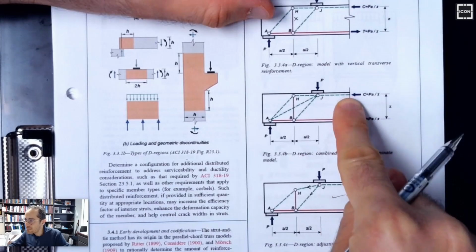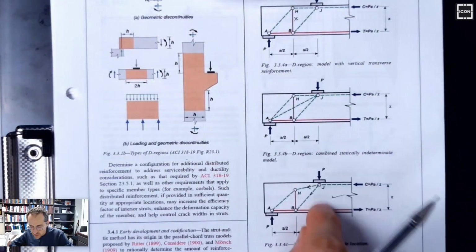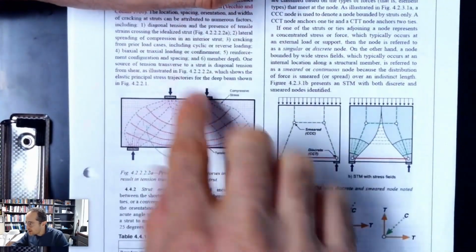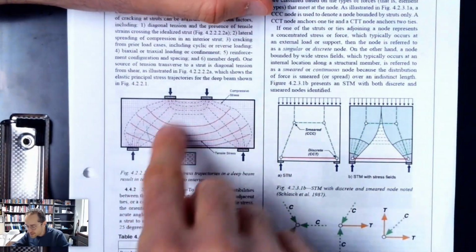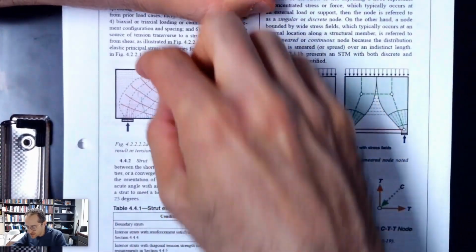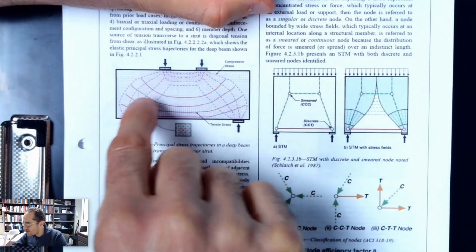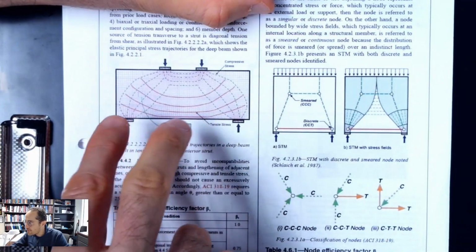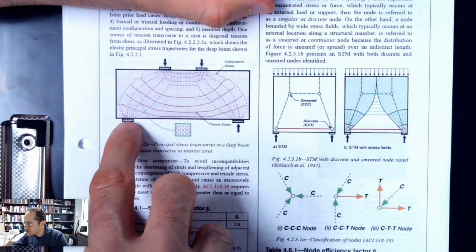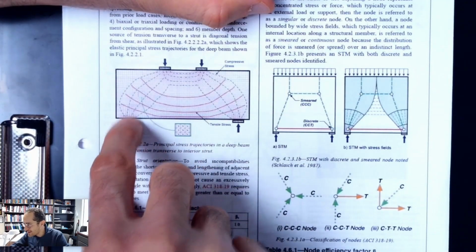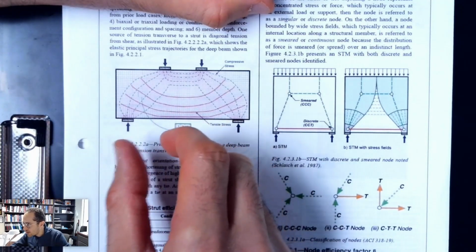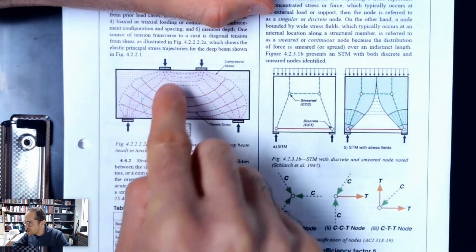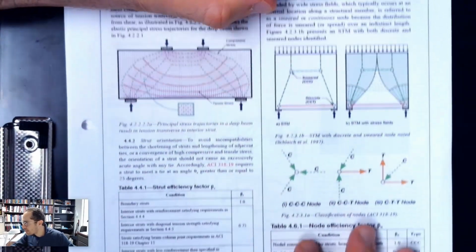This is definitely most complicated. You need a computer for doing that, so I would go with this one. I gave this one to you as a larger handout, so you can read the narrative, how this is developed. This is again a stress analysis. It shows how stress spreads. It uses larger concrete distances, but always we check it at the narrowest location. You remember we determined some concrete thicknesses, and I always checked it just underneath the bearing plate. That's the reason, because stress needs to really go into that shallow location, so we don't check it at a high location. We check it at the minimum cross-sectional location.